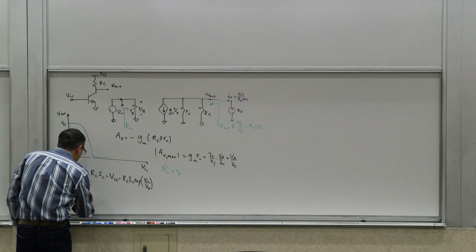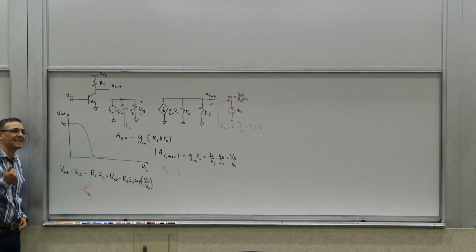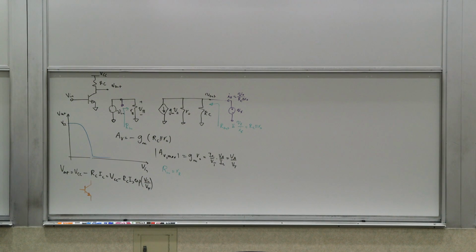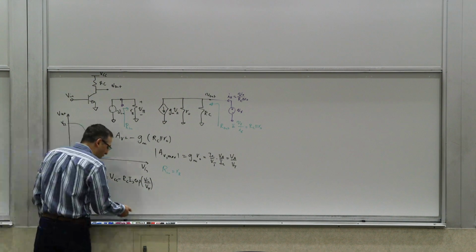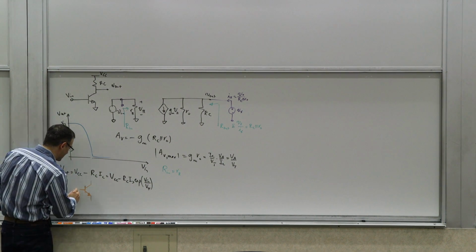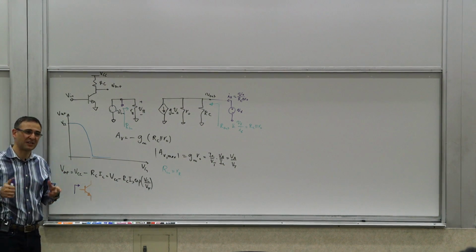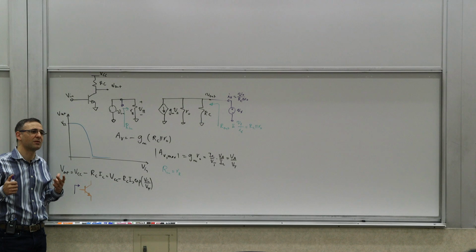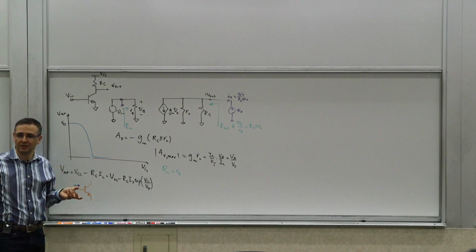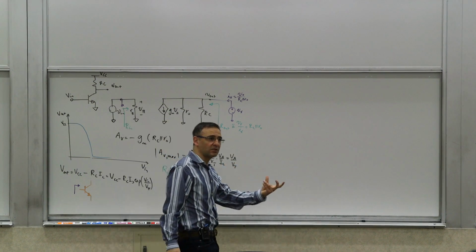But now in general, if you have a transistor, let's say a BJT, it's good to develop a sense about what are the resistances seen looking into the three terminals of the transistor. Not only what the values are, also get a feel for how large or how small they are. So let's talk about that briefly. So what is the resistance? And when we say that, we implicitly mean the resistance that you see if the other two terminals were AC ground, meaning that the transistor still is biased properly, so it's in the forward active region.